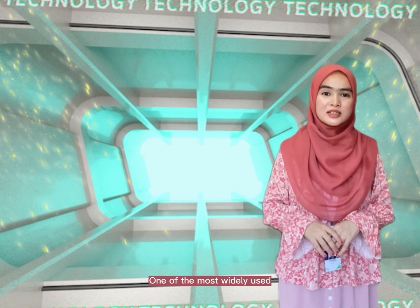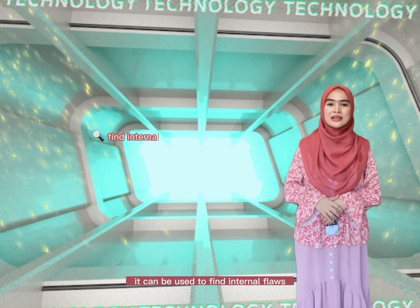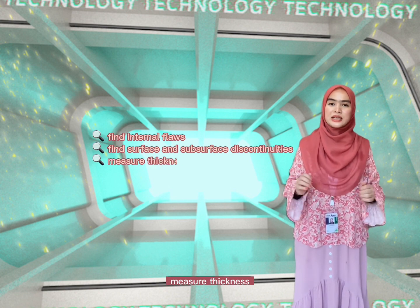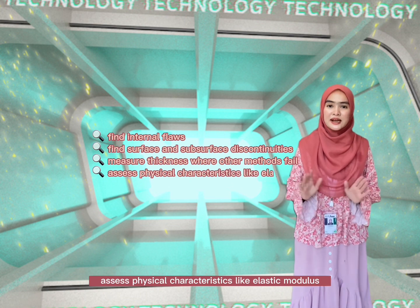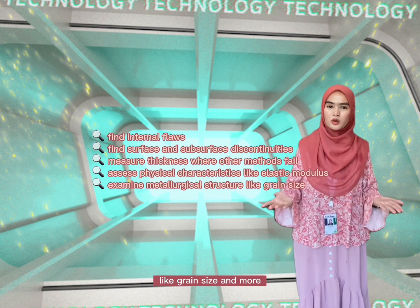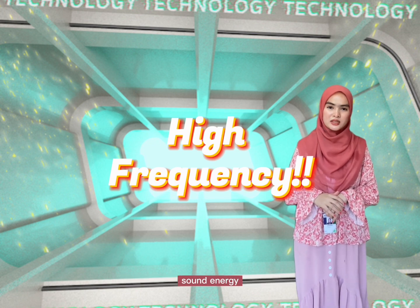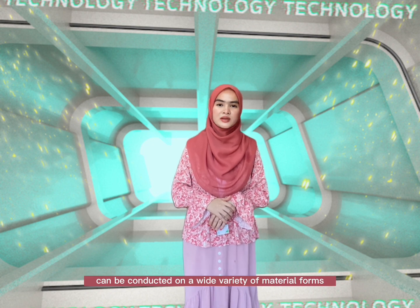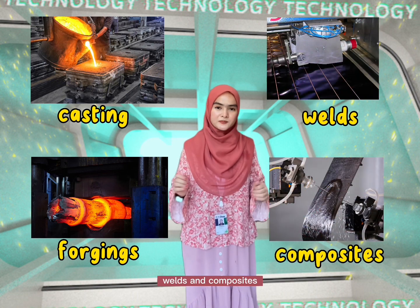One of the most widely used non-destructive testing methods is ultrasound testing. It can be used to find internal flaws, find surface and subsurface discontinuities, measure thickness where other methods fail, assess physical characteristics like elastic modulus, and examine metallurgical structure like grain size and more. Measurements and inspection are performed using high-frequency sound energy. Ultrasonic examinations can be conducted on a wide variety of material forms, including casting, forgings, welds, and composites.